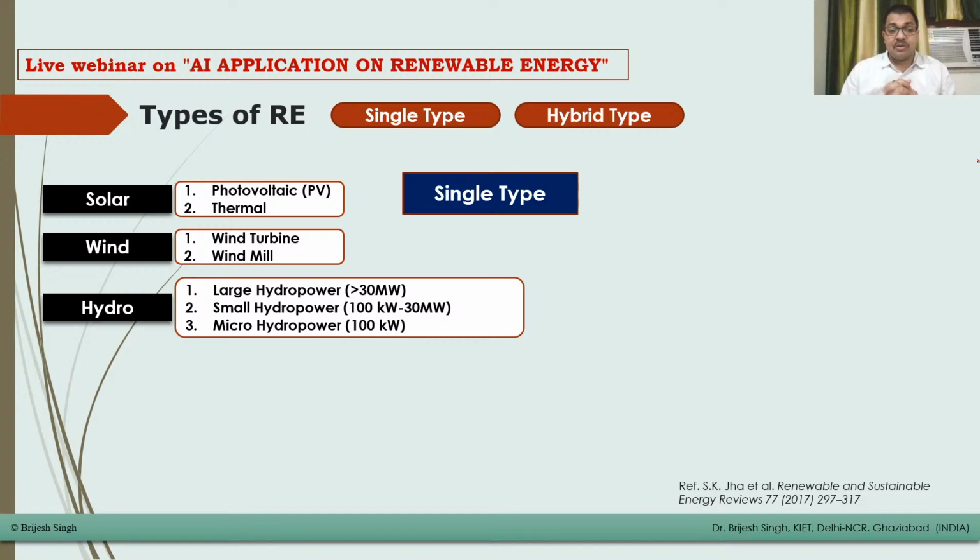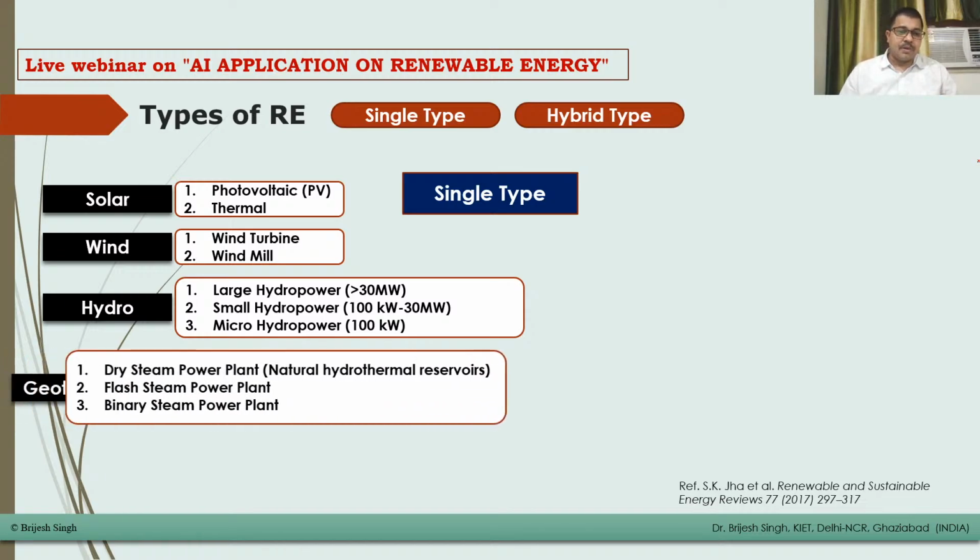And nowadays people are looking at micro hydropower plants, because the distributed generation concept came into the picture, and the second major promising area of technical work is the prosumer concept, where the consumer is producing the power. So micro hydropower plants come into the picture again. If you are installing a hydroelectric power plant below 100 kilowatt, it will work as a prosumer or distributed generation into the grid. These are the three major categories of hydropower plants.